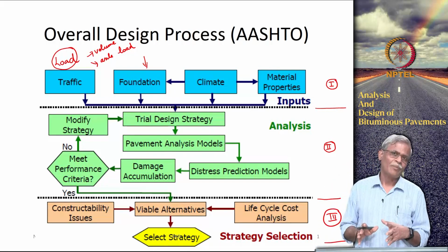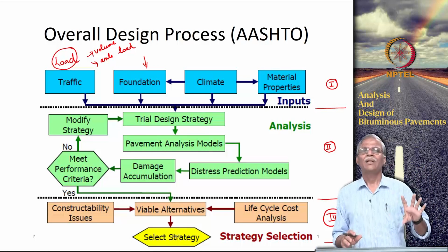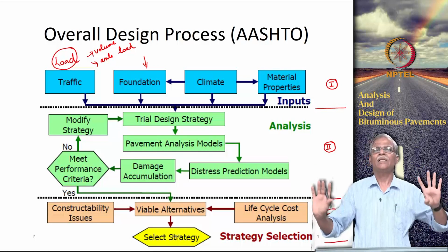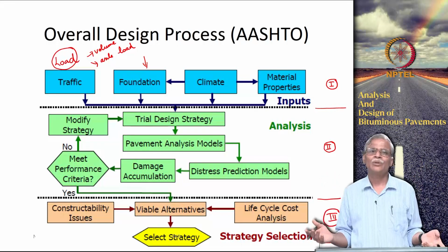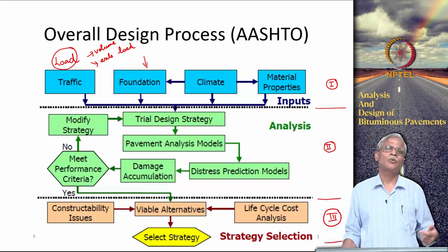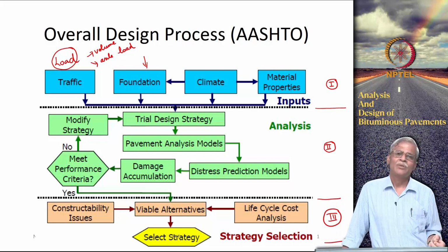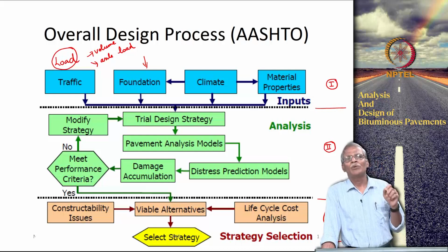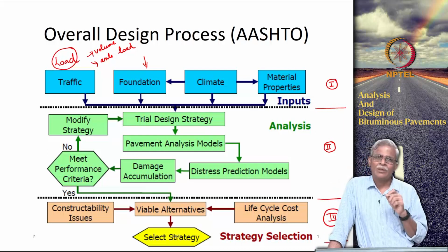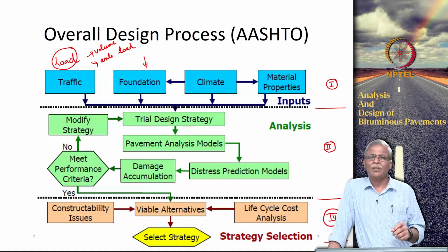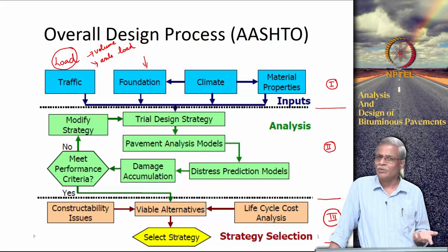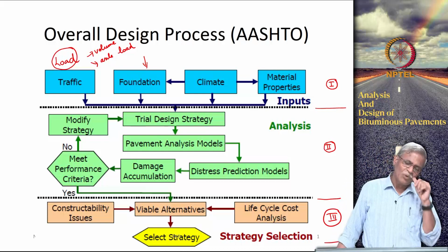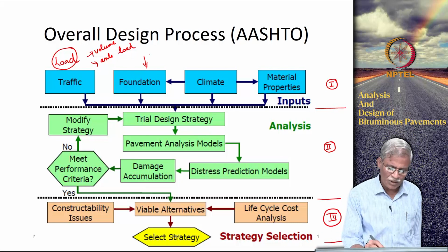The soil is the same, the road that you are going to construct has only some changes in the constitution, the layers, the type of materials that you use. But since the stress analysis procedure demands modulus of subgrade reaction for concrete, you will be measuring the same for the subgrade material, but for the same subgrade material, if you are going to construct a bituminous pavement, you are going to find out some CBR, some resilient modulus or something like that.